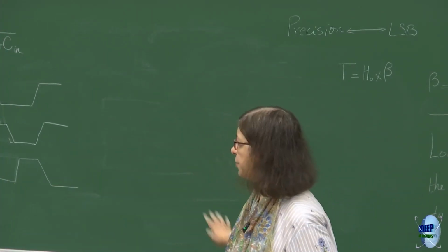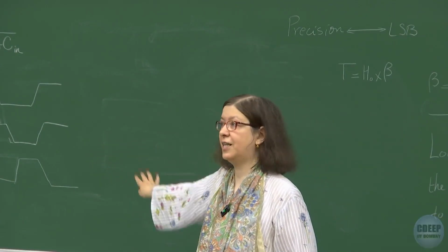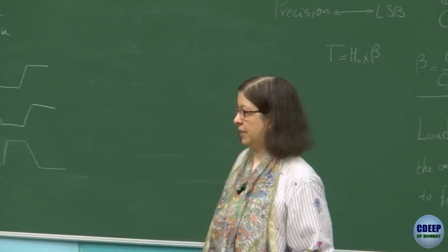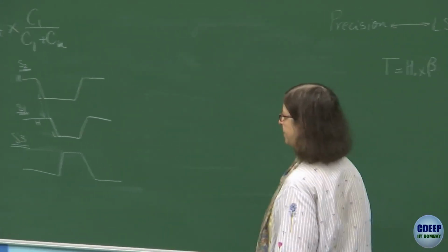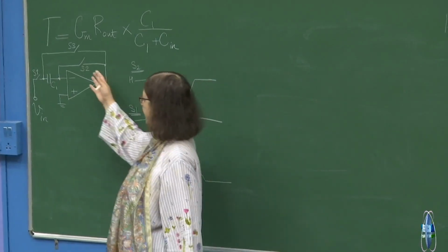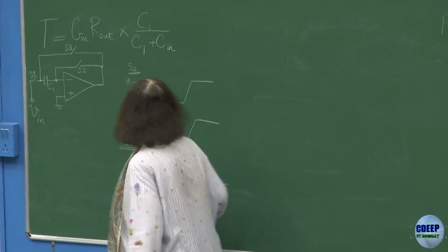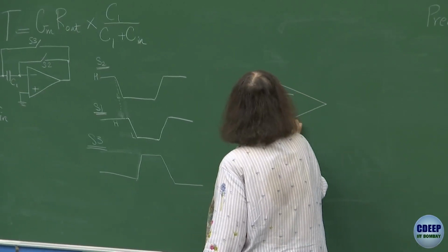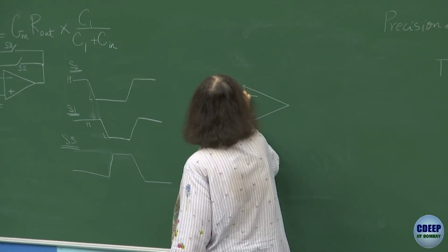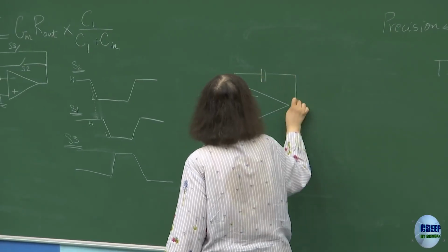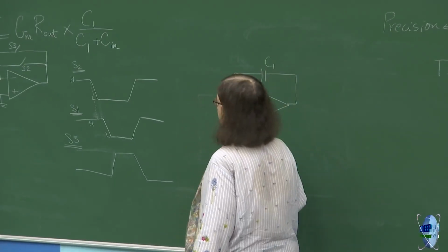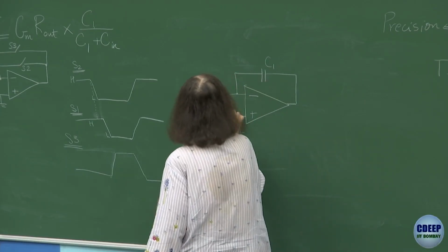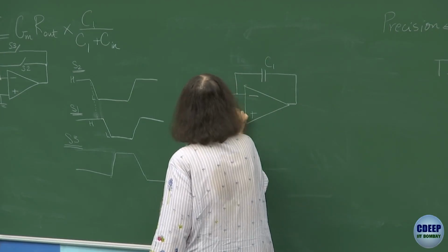Do you want me to talk about the charge injection cancellation in bottom plate switching here? If you want, I can repeat it here. After S2 is opened, S3 anyway is opened, you have this circuit. I draw Cin because saying Cin is 0 is not useful, since anyway it is there.